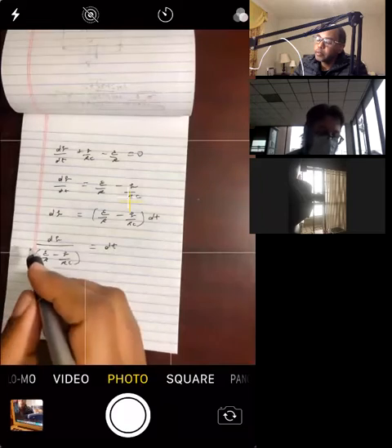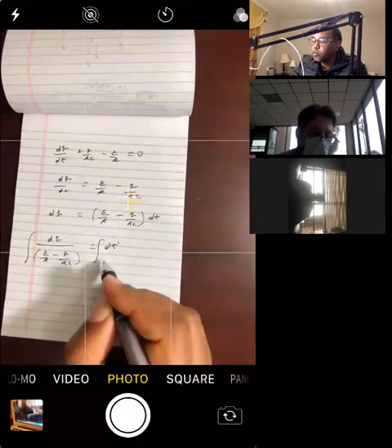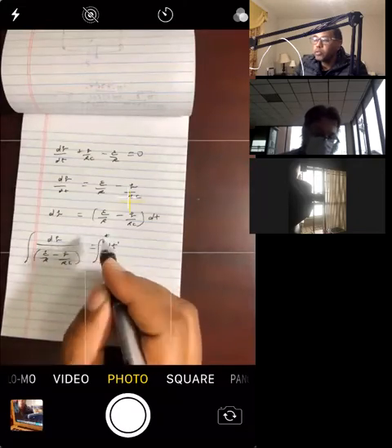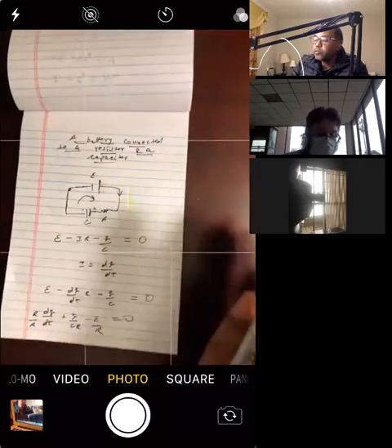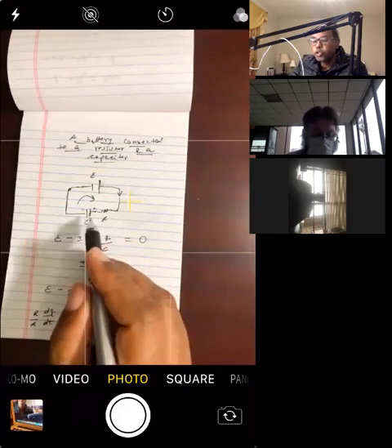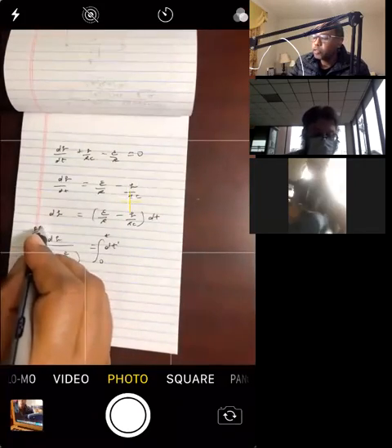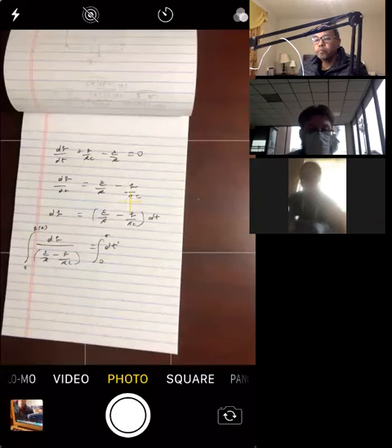So we can integrate now. The time obviously goes from 0 to t. How about the charge? We're starting with a 0 charge for the capacitor, but eventually we'll keep building charge. So the charge starts from 0 and goes to the charge as a function of time. This is our integral.